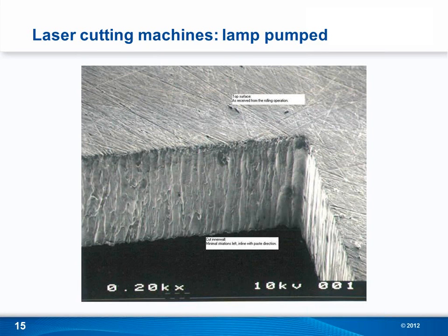This particular picture has a slightly higher magnification than the previous one, so the striations do show up clearly, but the top to bottom depth of the striations is so shallow that the impact on paste release is minimal.